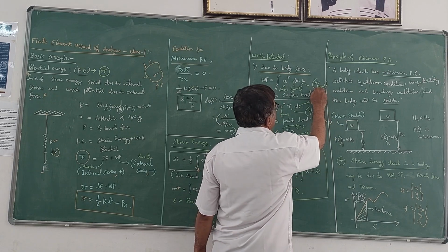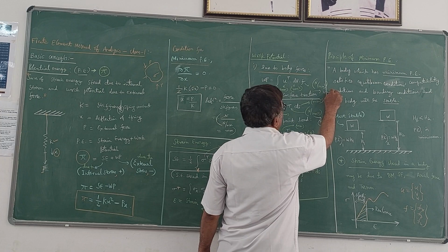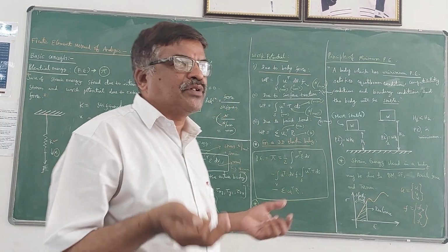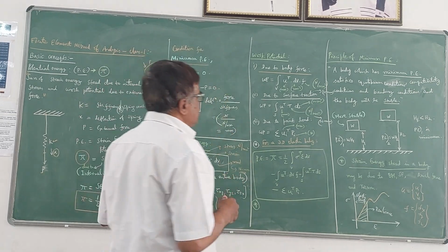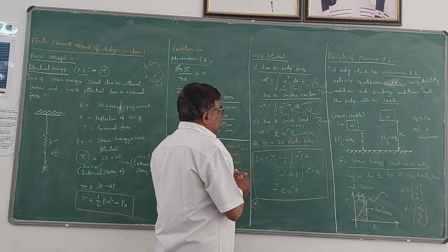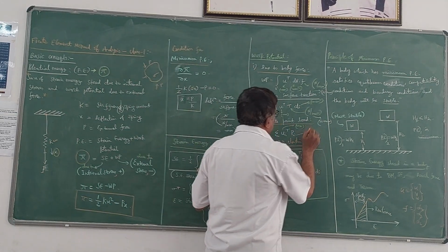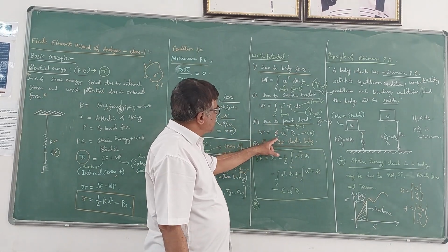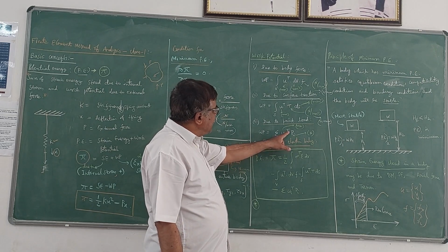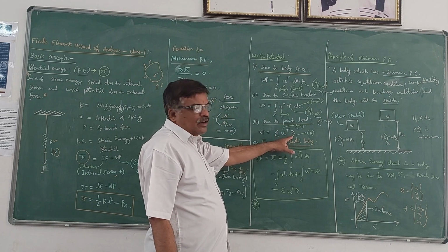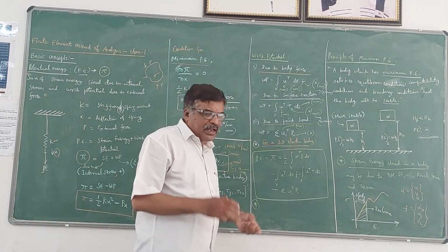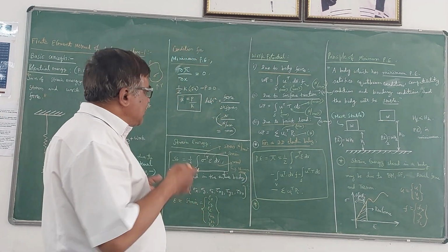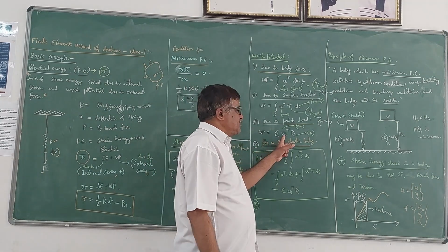Here also you will be getting Newton millimeter if you multiply all the three units, because the work done is expressed as force into displacement. Now due to point load, work potential is expressed in a discrete form: summation of UI transpose into PI. That means PI represents the point forces acting on the body, a linear force, into the displacement vector.